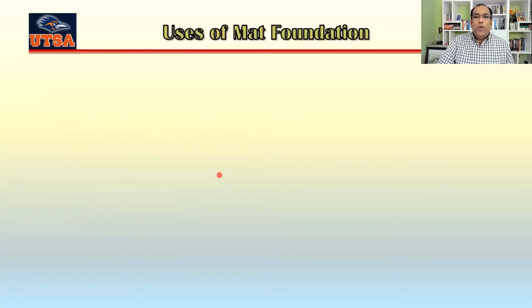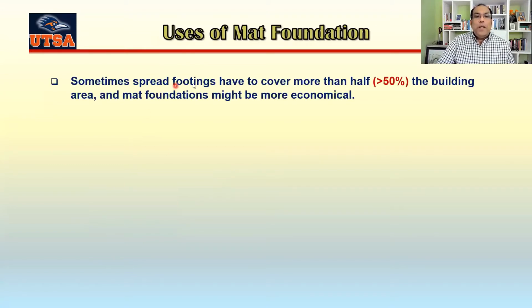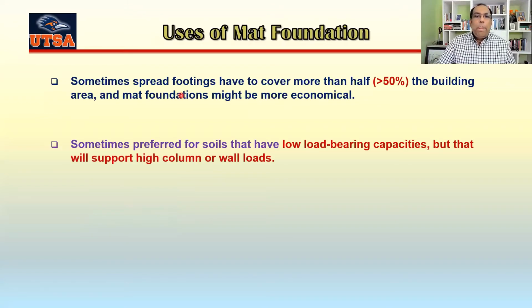So, use of mat foundation: when do we use mat foundation? First of all, if the spread footings have covered more than 50% of the building area, the mat foundation might be more economical. Rather than cutting separate individual footings for each of the columns, just cutting the whole area and then constructing the mat foundation would definitely be more advantageous. Second, it is sometimes preferred for soil which has very low bearing capacity but the column load is very high.